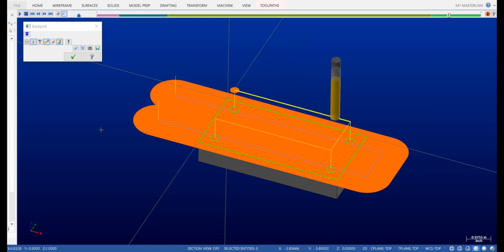Let's take a look and see what the multiple part operation would look like on the machine, and then let's take a look at the code and how we would format it to use the same code over and over at multiple stations using M97 and M98 commands.